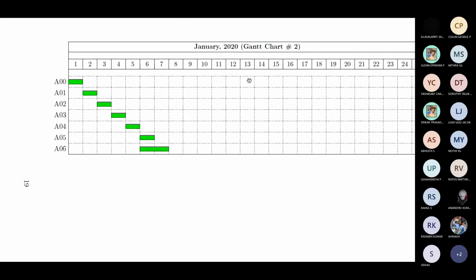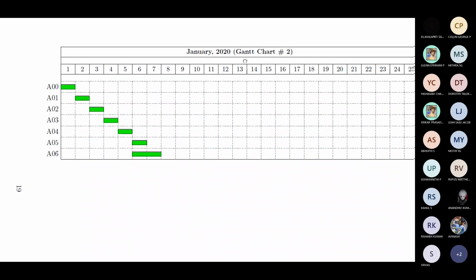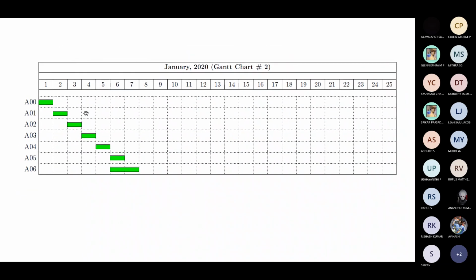Right. So for Gantt, note the spelling, it is Gantt. Generally, people forget the double T. They just provide a single T, but it's named after the person who developed this chart, Henry L. Gantt. Right. And A00, as I told you, is the site clearance, and A01 is the surveying. You cannot do surveying before clearing the site. That will give an inaccurate result. This may not be as comprehensive. So that's why generally people do site clearance first, then they look into the other aspects like surveying.